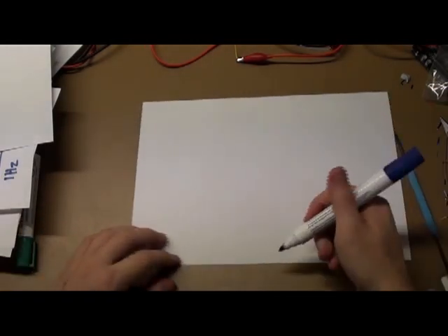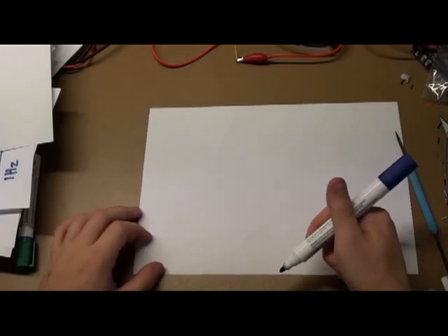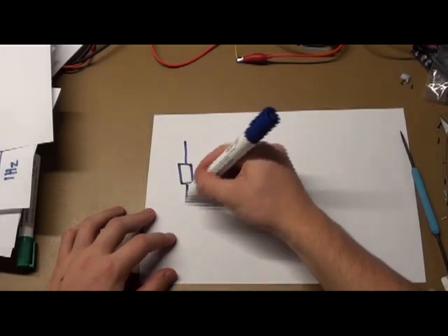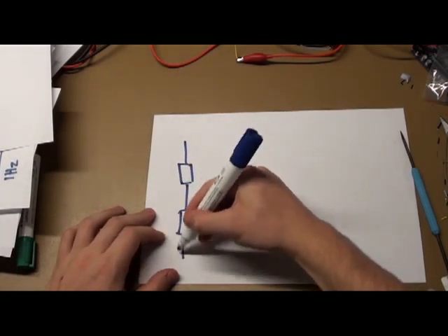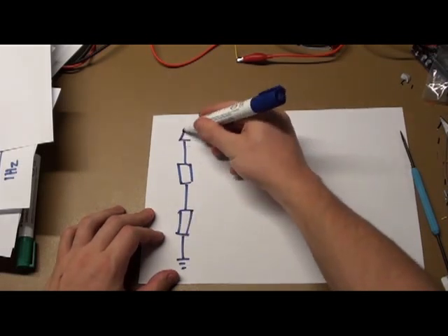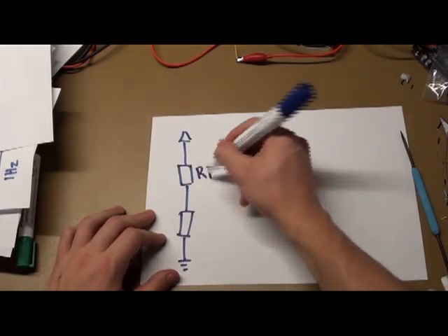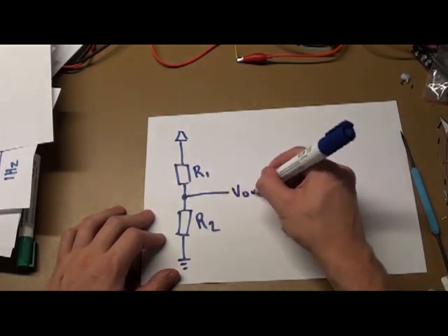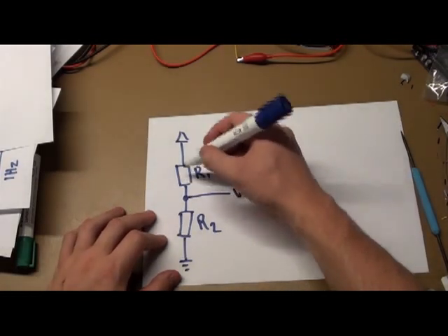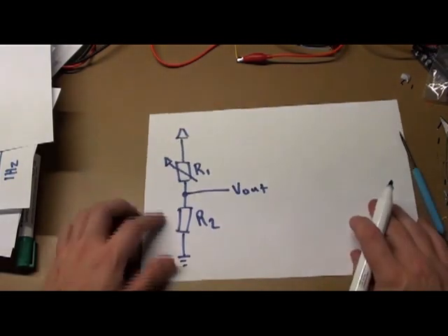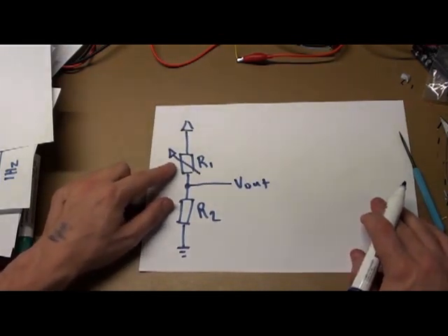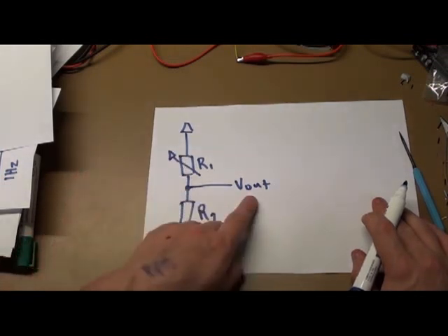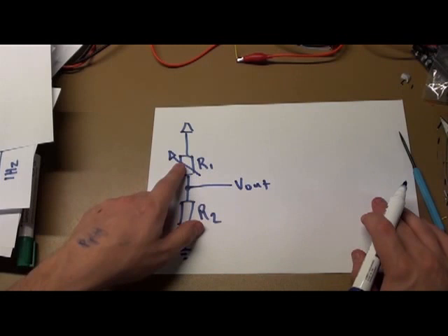So now that we've gone through all these amplifiers and we know what frequencies are, you might be thinking that our original voltage divider, so this is R1, R2, this is V out, and this one changes with strain. So you might be thinking, if we can put the strain one here and we know this one, can't we just work out V out when this guy changes?